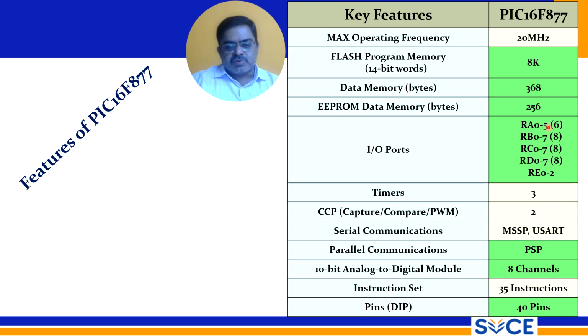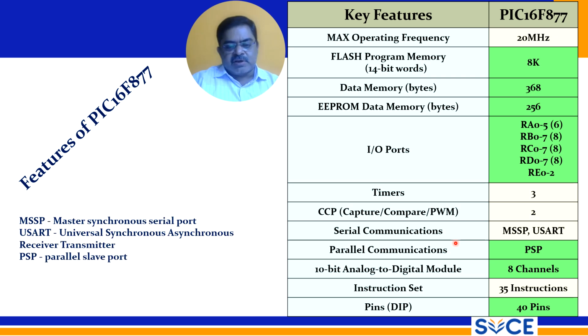IO ports, and 3 timers. CCP, capture, compare, and PWM, pulse width modulators, 2. And serial communication MSSP, that is master synchronous serial port.